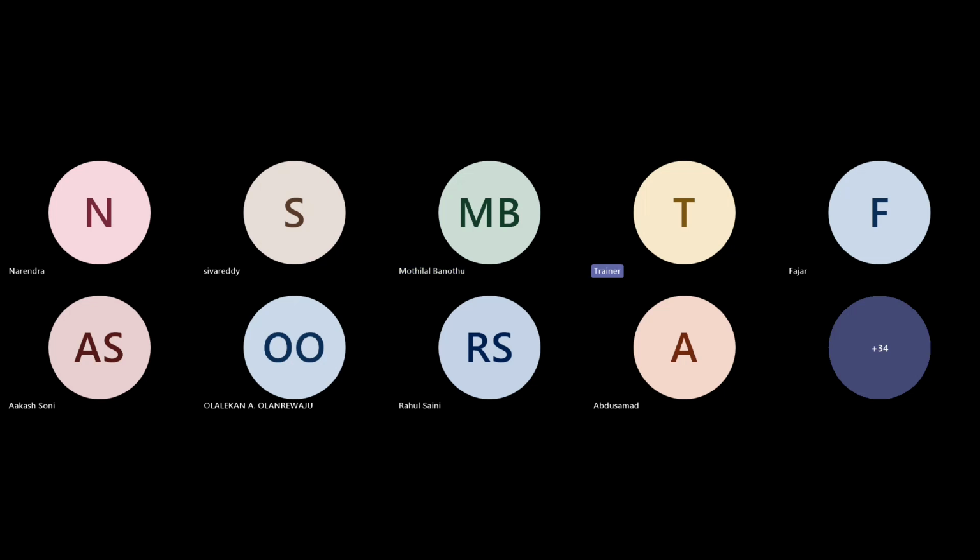And we are considering this as a continuous process. So feed is coming, vapors are going, liquids are going. Even if your liquid level goes from low liquid level to high liquid level, the vapor side is open. The effect of this height change is generally 600 mm, so 0.6 m. You can consider rho g h, and calculate how much pressure change you can observe.